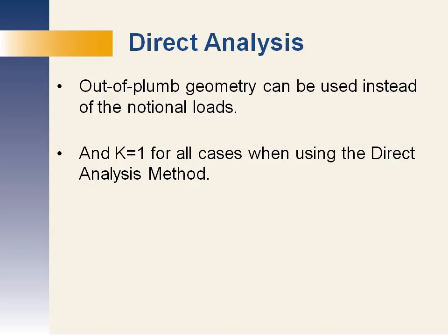And this is an effective way to go about the analysis. You can eliminate the notional loads at that point and perhaps simplify things. And in the end, that's it. By softening the frame and increasing the drift, we get the forces and moments that can be used in design with K equals 1. So that's pretty simple, right?